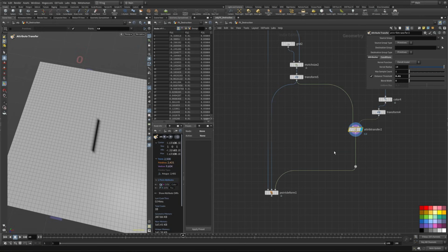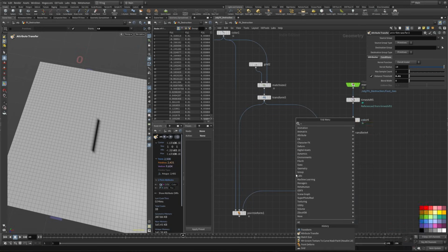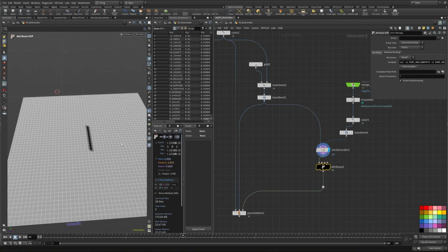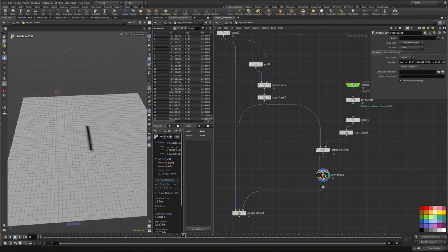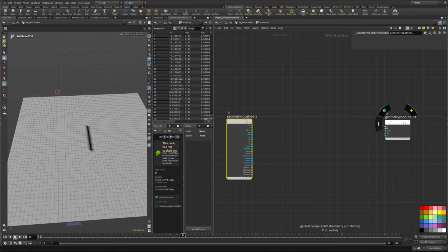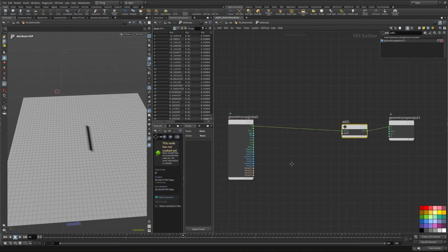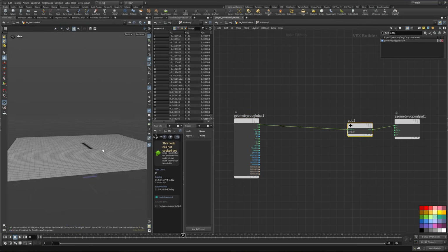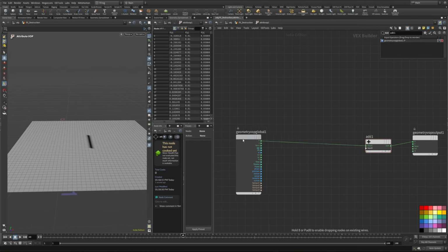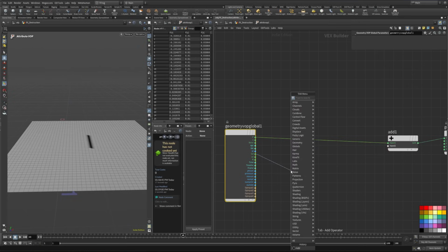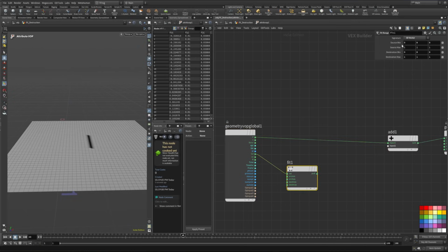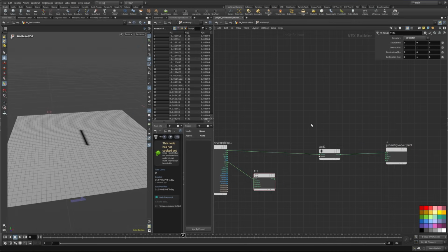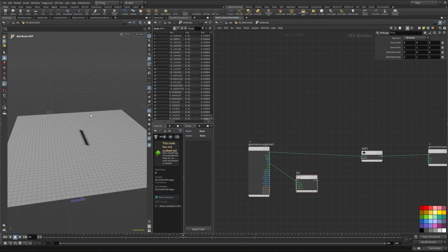And they're not moving down now because we need a VOP for this again. So we're using an attribute VOP. But we can use the color now to move them down. And for this, we're diving inside. And we plug the position into the position. And we want to add that the points are getting dragged down here by the color. So we need our color going into a fit range. And my 0 should go down. And I only want to move them into the y direction.